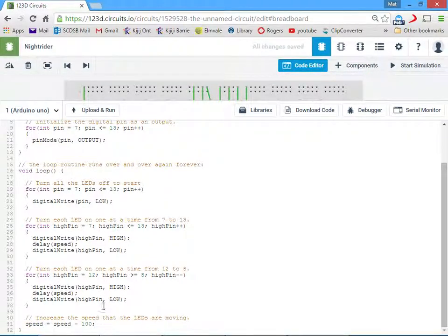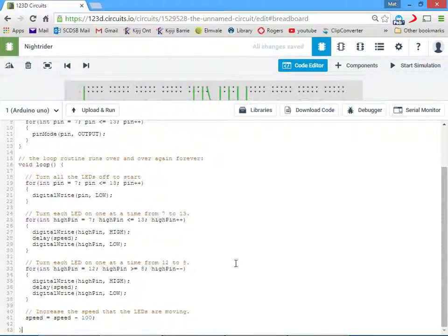and then it starts going into the negatives. So we're delaying 0, which is nothing, then we're delaying a negative amount, which I'm sure probably just gets converted to 0. It's probably just ignored in the microprocessor. And then we just keep going, and after this runs for a while, speed probably goes into huge negative numbers. So if we want to limit this delay, so say we want to start it at 500, but we want it to stop. We never want the delay to get less than 100.